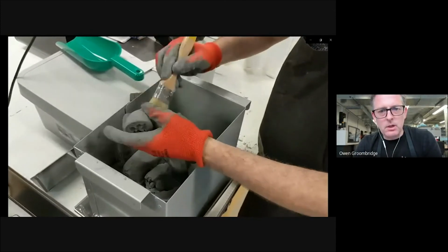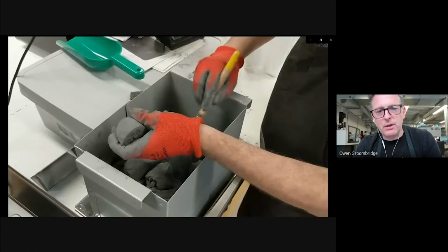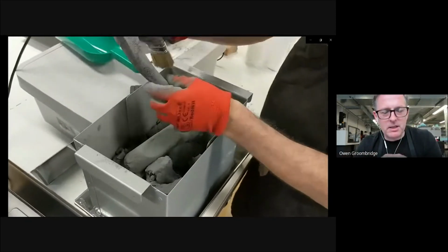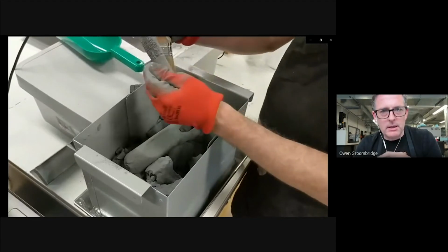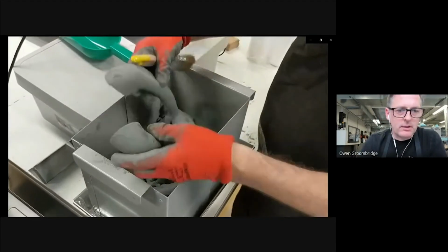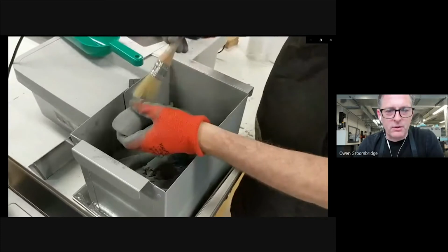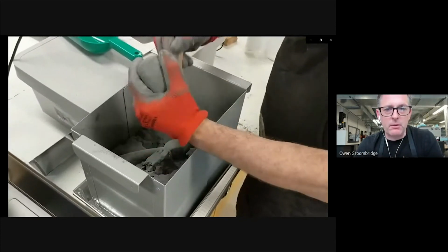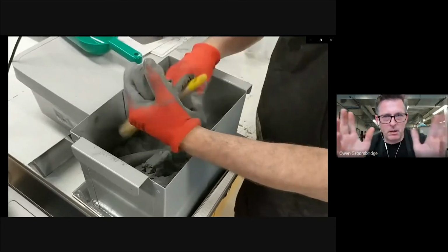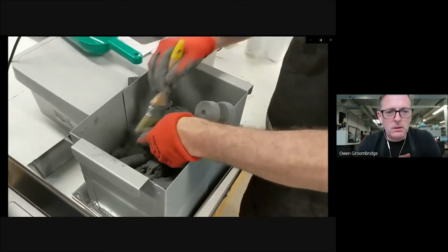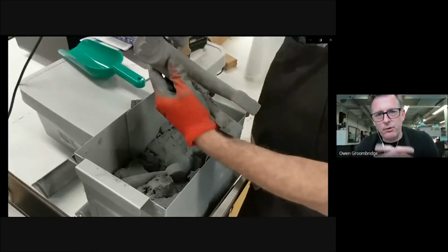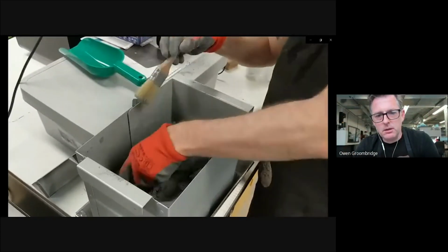Okay. So cleanup is a bit of a faff because you've got to get this powder off. So we use a brush. You can imagine this stuff getting everywhere. And you can just notice there, actually, part of it, the finish doesn't look so good. That's because the powder really wasn't mixed properly. That was probably virgin powder, so to speak. Once we've got most of this stuff off, we put it into a shaker.